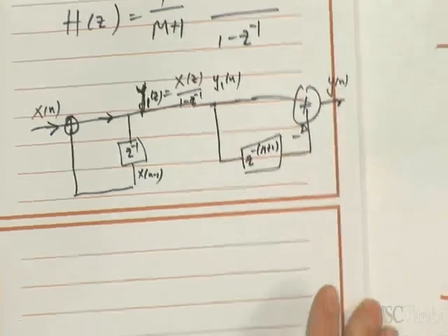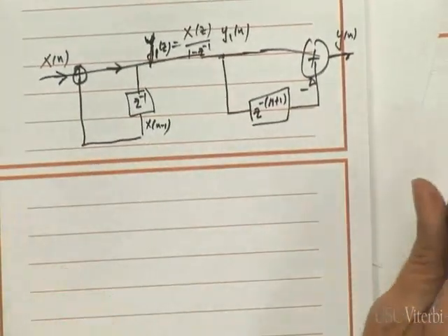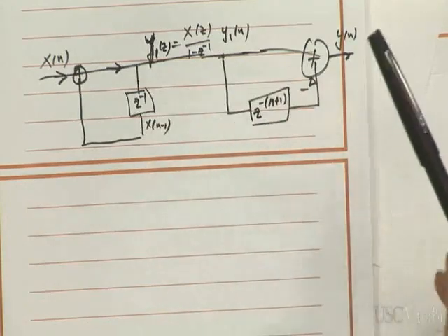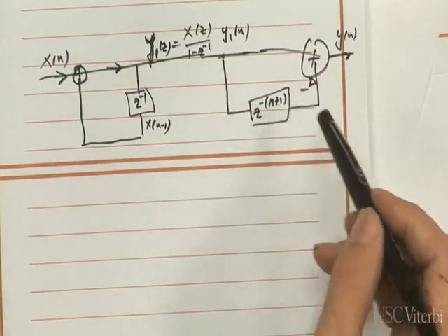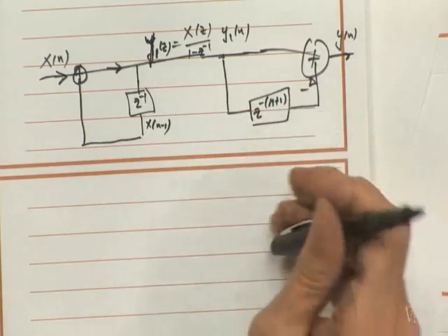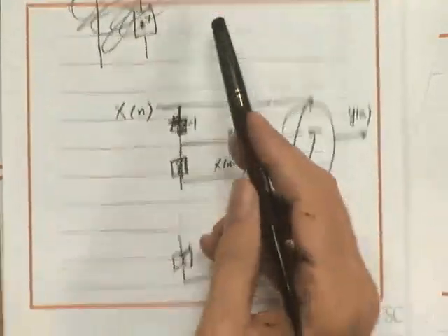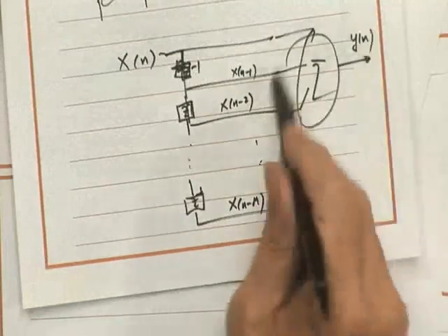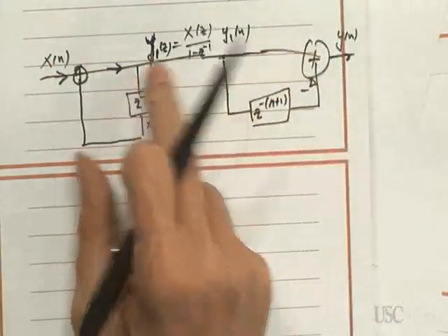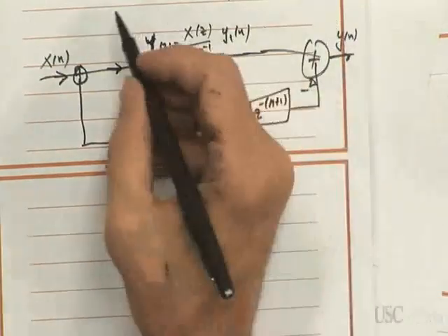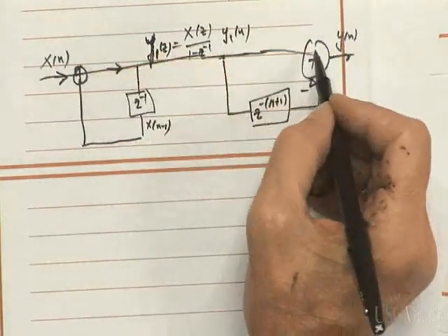Actually, you have to scale it, but I won't worry about that for now. So here is another way. Now, it's true that you have multiple delays, but you don't have to do this, where you're tapping all these signals off and summing them. Here you basically have one delay here, one delay, and guess what? You have one and I think two adders.